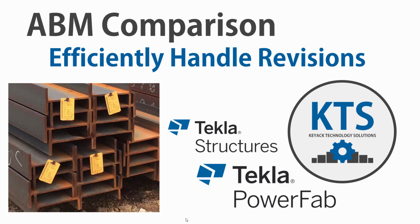In this video today, I'm going to talk a little bit about ABM revisions. And this is something that has been a thorn in my side in Tekla Structures for quite a long time. If you work with large fabricators, it can sometimes be a significant process trying to do add and drop reports for them, especially throughout multiple ABM revisions on the job, even after you started connecting. So here I'm going to show you a process that helps the detailer and the fabricator work together to deal with these revisions and prevent costly, up to thousands, if not tens of thousands of dollars in material mistakes and not communicating changes properly, especially on a job that's got a lot of revisions.